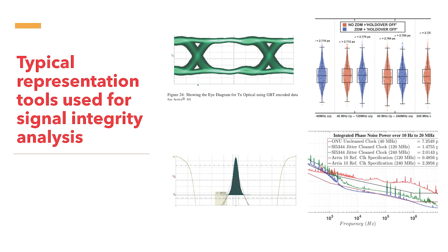One that you already know from your BTech studies is the eye diagram. The opening of the eye diagram gives you the quality of the signal. The eye height will give you any type of amplitude distortion, and eye width will give you any type of timing distortion.